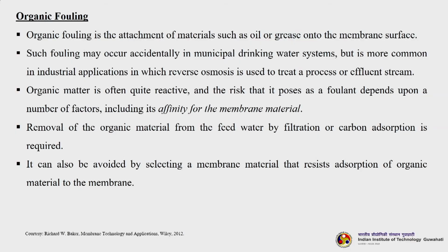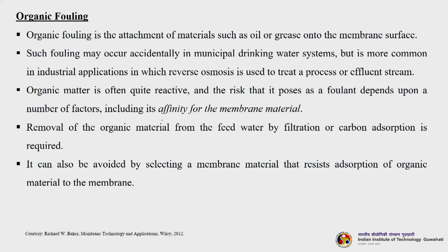such as refineries. Organic matter is often quite reactive, and the risk that it possesses as a foulant depends upon a number of factors, including its affinity for the membrane material. One of the most important things for these organic compounds is their affinity towards the membrane material. The affinity depends upon the type of membrane material and of course the properties of the organic compounds. Removal of the organic material from the feed water by filtration or carbon adsorption is required. It can also be avoided by selecting a membrane material that resists adsorption of organic material to the membrane.